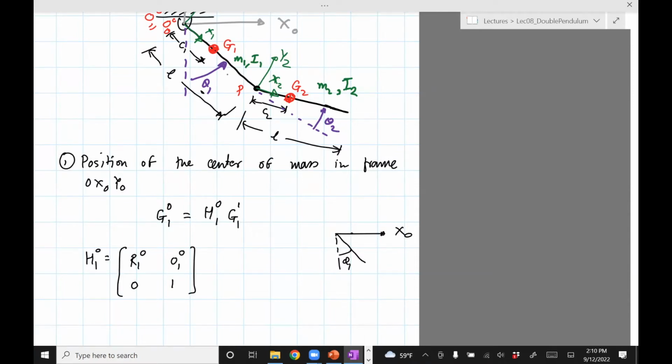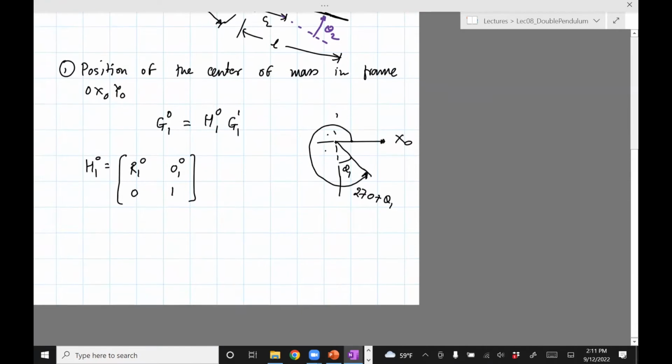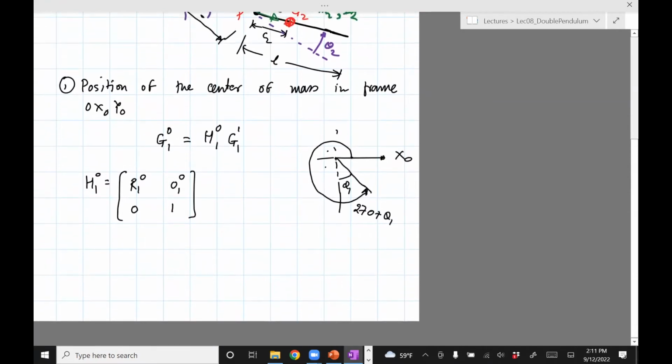So if you want to compute that angle, you need to go all the way here. And so that angle is, well, it's 90 plus 90 plus 90 plus θ1. So it's 3 times 90, which is 270. And so that's the angle which will go in the R. So that formula which I had for R needs that angle. Okay, now there are other ways to do it, which is you can define a clockwise angle and do it that way too. I just think it's better to stick to the convention which you used.